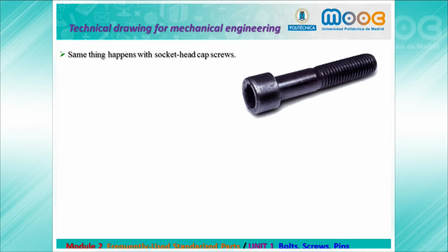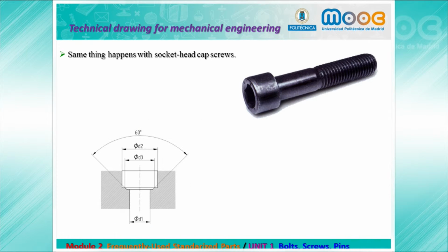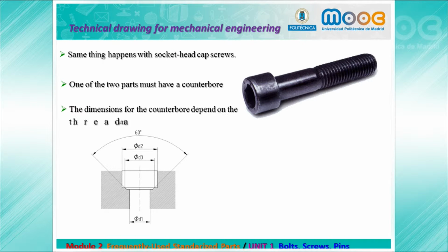Same things happen with the socket head cap screws. One of the two parts must have a counter bore, and the dimensions of the counter bore depend on the thread and the standard. So in this case, these are the dimensions for the counter bore.